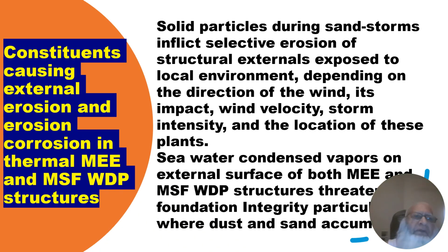Constituents causing external erosion and erosion corrosion in thermal MEE and MSF-WDP structures. Solid particles during sandstorms inflict selective erosion of structural externals exposed to the local environment, depending on the direction of the wind, its impact, wind velocity, storm intensity, and the location of these plants.